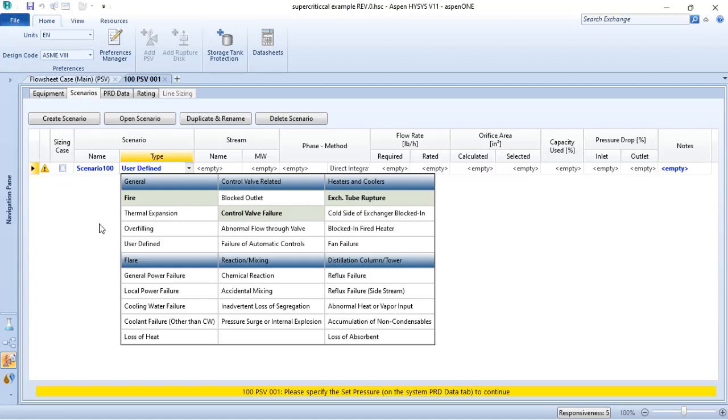Most often, the downstream process is not able to reach the same amount of pressure that the upstream of your control valve has, and because of that, you need to consider pressure relief devices to prevent the rupture of your system.